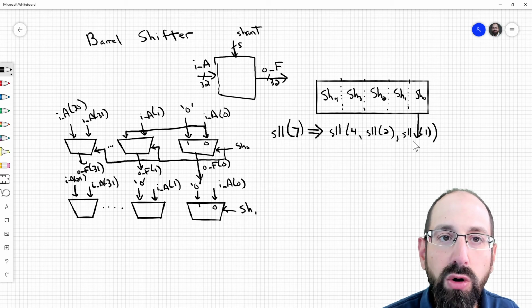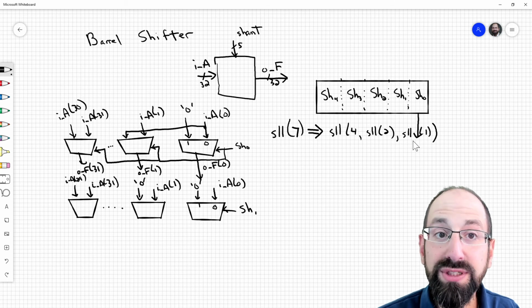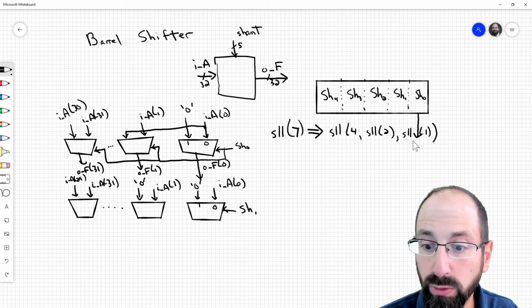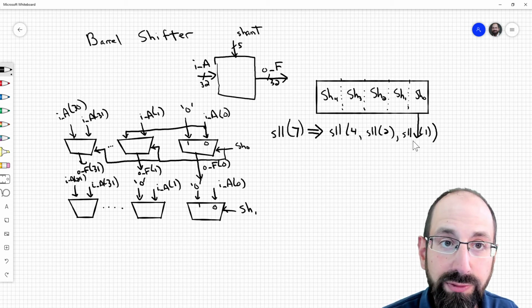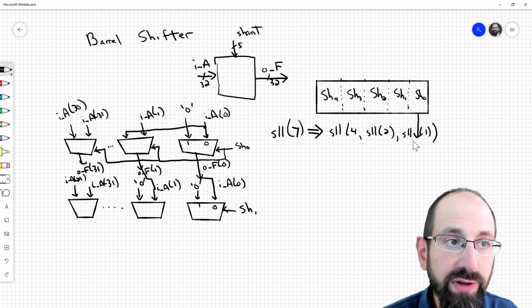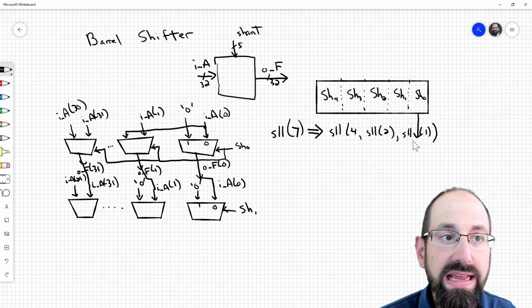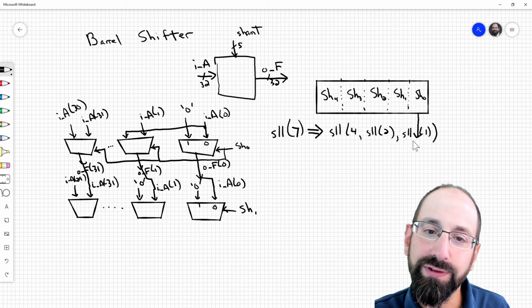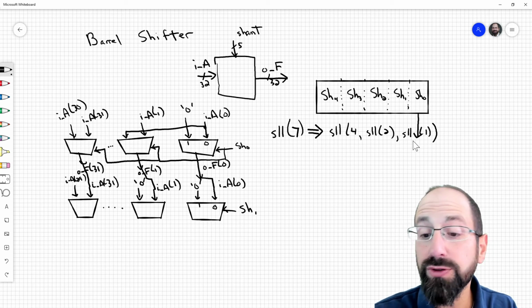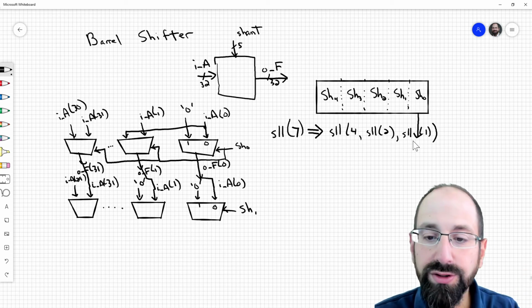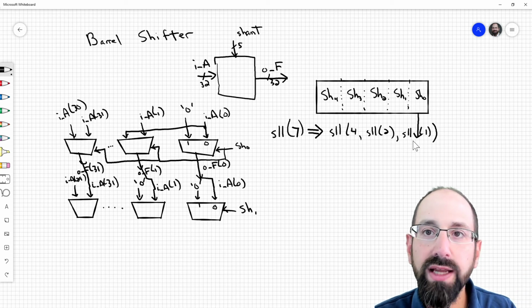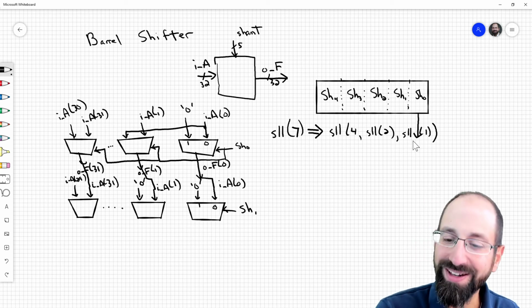Literally, what we called OF isn't actually this OF. That's the intermediate result of having potentially shifted 1 bit to the left or not. And we can connect that directly into the input. Right? And VHDL allows us to wire our signals accordingly into the input of our next level of shifter. And you would just do the same. That's a 1 shifter and a 2 shifter. You'd also build a 4 shifter, an 8 shifter, and a 16 shifter, and then you would be done.